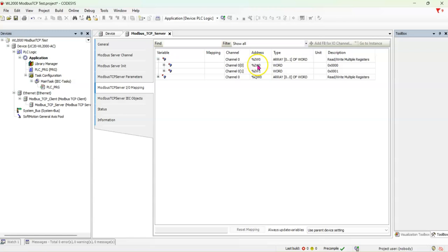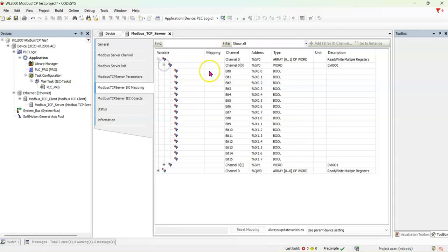So they're coming in to the PLC and they come into register IW0, and from the second card they come into IW1. And if you notice, you can expand them and they are at bit level. So because one card was a 4 channel using 4 bits, it will be these 4 bits, and the other card was 16 bits, so it would be using 0 to 1.7.